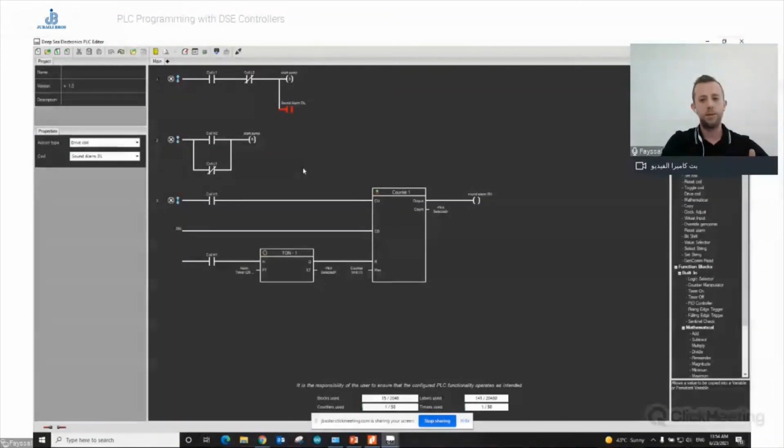So how do we do this? If my H1 switch is active, that means my fuel level exceeded the high level switch in the bulk tank, then I'm feeding this into a counter, and I'll explain why we are using a counter here.